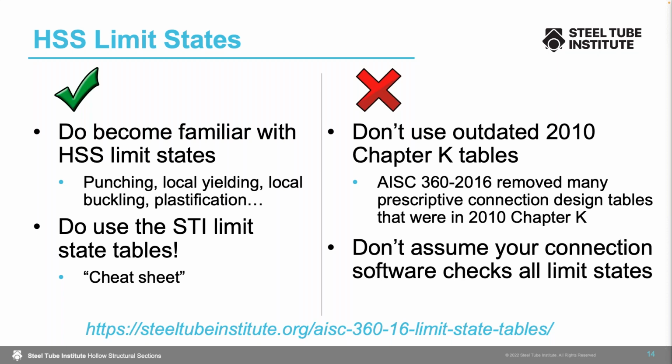Another don't that we want to point out here is don't assume that your connection software checks all of the limit states. Now, what we recommend is that you do a verification example up front, because there may be some limit states that aren't incorporated yet into your connection design software. So just a heads up that that could be something that is overlooked.